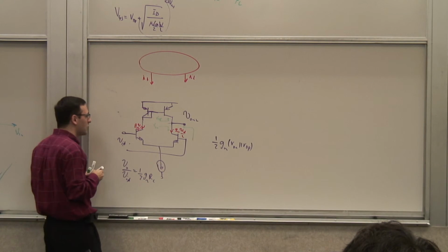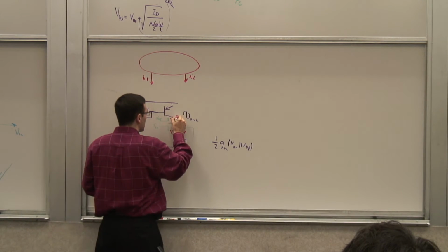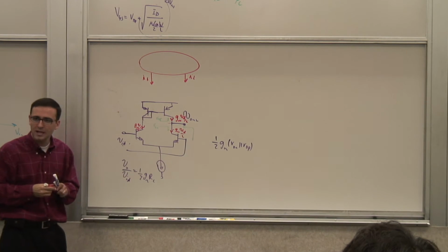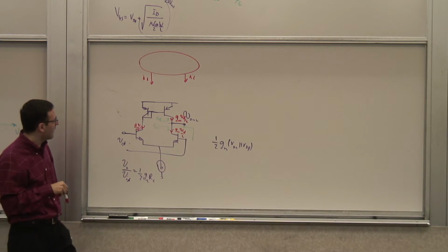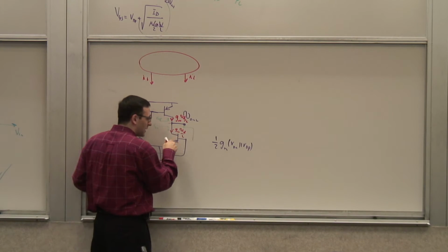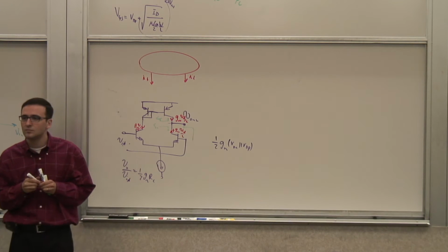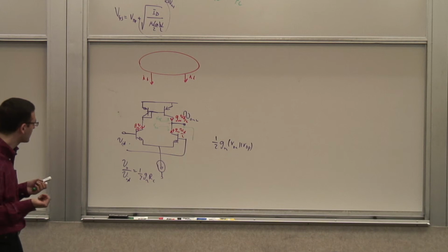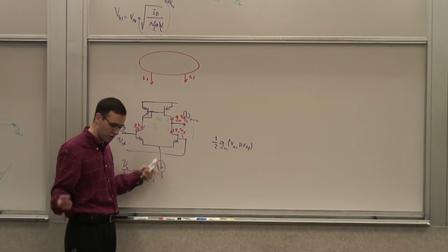And replicate it. So if I do this, what happens is that I'm pulling this current out of here, so it pushes this current in, which is GM VID over 2, right? That current is being pushed into that node. Is it fair to say that this current being pulled out is equal to this current with the opposite sign being pushed in? Just change the polarity and the sign. So now, both of these are pushing current into that node.